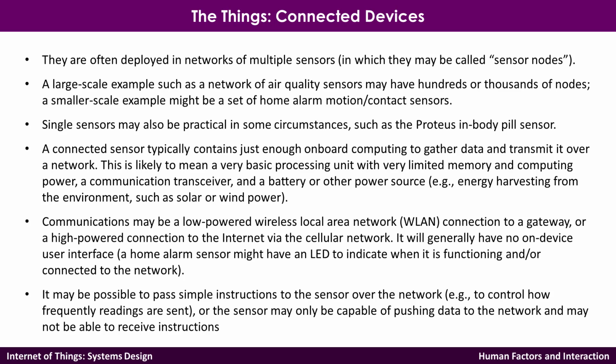Can you send the data once a day? Can you reduce or aggregate the data within the connected sensor? Or you can activate the sensor when a particular event happens. Like if it is an intruder detection system, where you only need to send the data if the sensors detect some kind of motion.